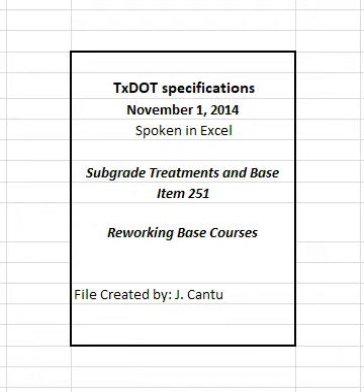4.2.4 Reshaping. Rework scarified base material with or without additional new base material. Mix and shape scarified base to conform to the typical sections shown on the plans. When shown on the plans, furnish new base material, and uniformly mix with scarified material before shaping. Do not disturb the underlying subgrade. Correct, or remove and replace, segregated material with satisfactory material as directed.